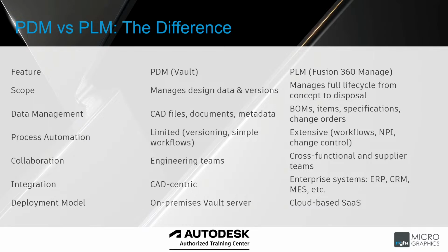The big difference between PDM versus PLM. Your scope, PDM manages your design data and versions. Your PLM manages your full life cycles from concept to disposal. Data management, your CAD files, documents and metadata, and your PLM has your BOMs, your items, your specifications and change orders. So the PDM also does have your change orders if we think about Vault Professional.